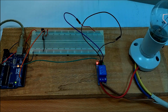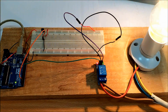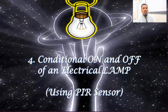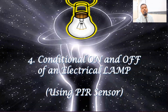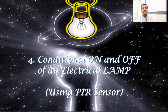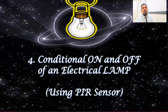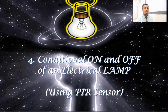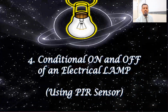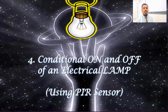So the next category of control we are going to discuss is the control of the same electrical lamp using a PIR sensor, normally called a human motion sensor. Next, what we are going to see is conditional on and off of an electrical lamp using a PIR sensor. PIR stands for passive infrared sensor. Another simple name for this sensor is motion sensor, because this sensor is used to find human motion. So when people are moving around, this sensor will pick up that movement and it will be delivered to us through the output pin of the sensor. That sensed motion, we can use for controlling our lamp.